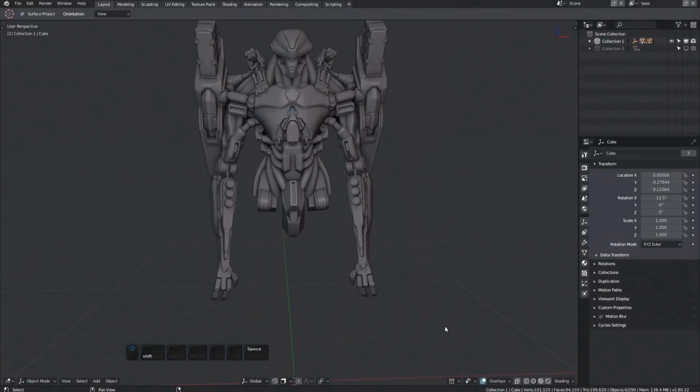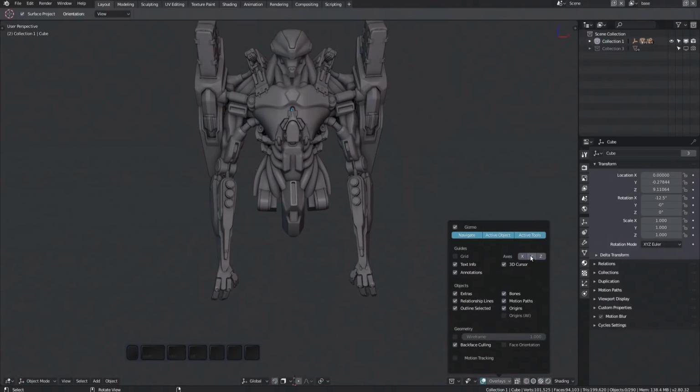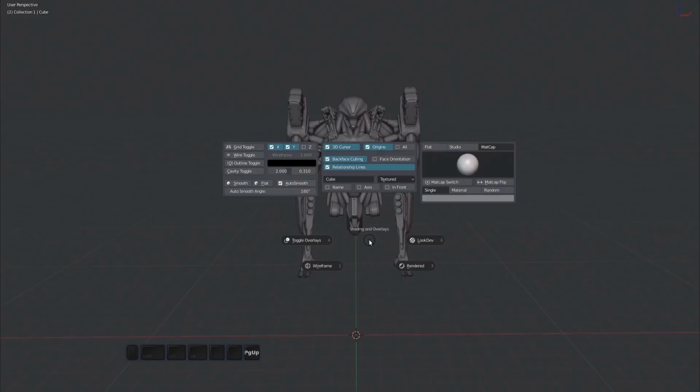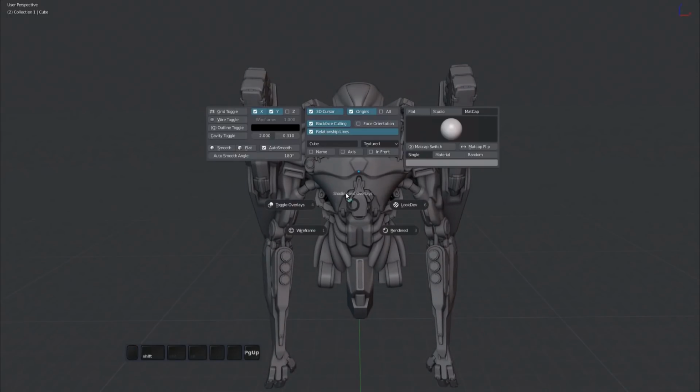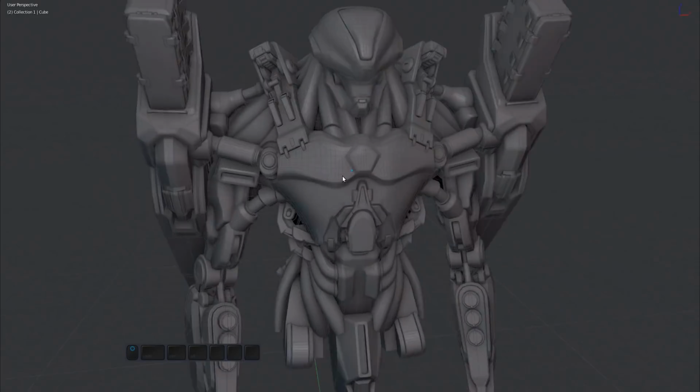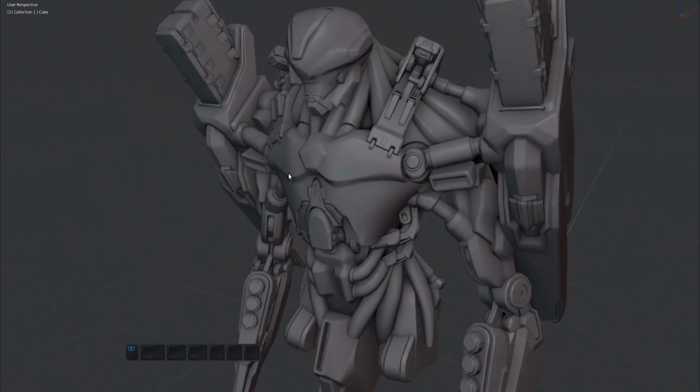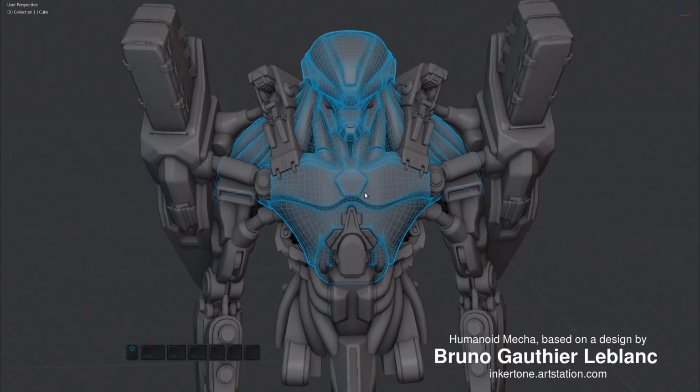The default way to toggle the grid is quite cumbersome. Notice the underlined letters in the buttons, which can be used to very quickly access these toggles. I just bring up the menu, followed by pressing G for the grid toggle. The wire toggle is used in the same way, but is a bit more complex and does different things.